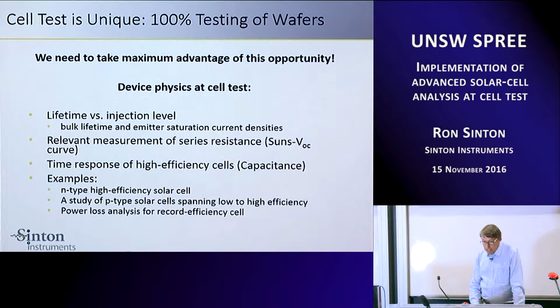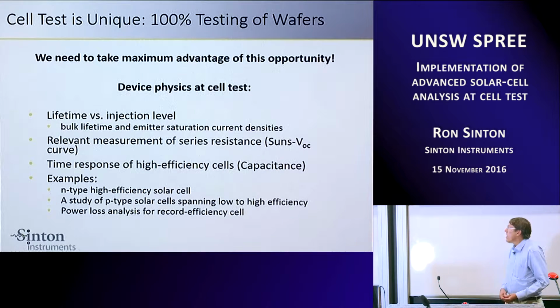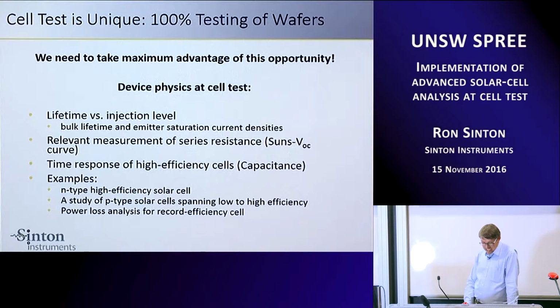And so we need to take the maximum advantage of this opportunity and do some device physics at cell test. And of course, we're going to measure, and I'll talk about in this talk, lifetime versus injection level, the relevant measurement of series resistance, which we use Suns-Voc. I'll talk about the time response of high efficiency cells, and I threw in a few extra slides after talking to Allison yesterday about this. And then some examples in the end.